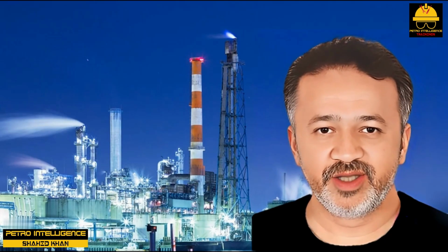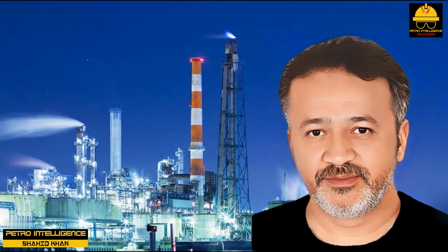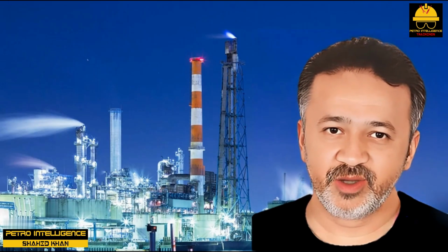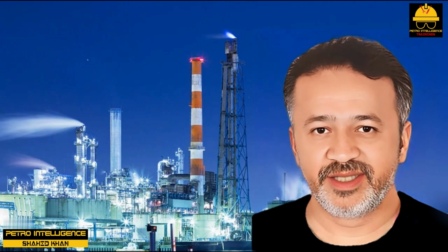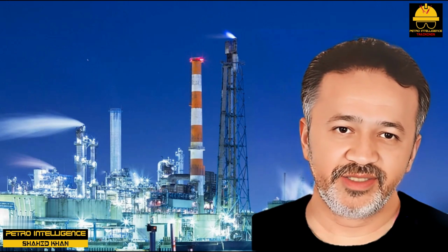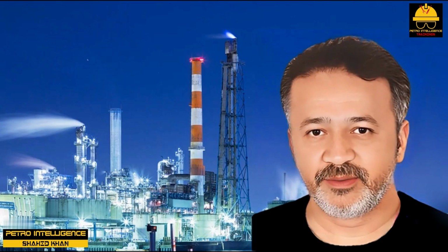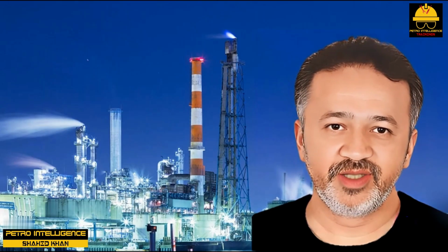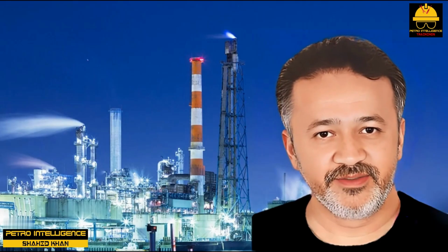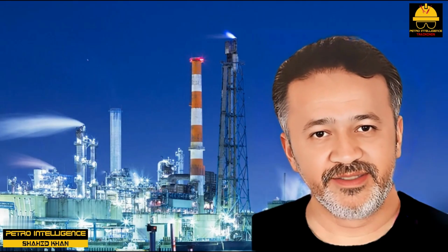This will raise the compressor discharge pressure. Also, the operating pressure on the shell side of the condenser will increase. If either piece of equipment does not have an adequate design pressure, then increasing the volatility of the refrigerant cannot be permitted. An engineer used this trick at the refinery to increase the refrigeration capacity of a sulfuric acid alkylation unit.